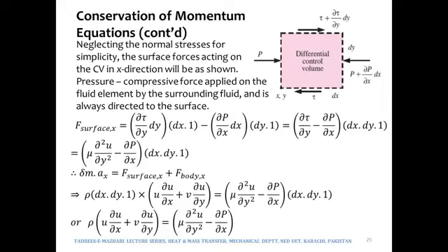So the same form of Taylor's expansion has been made use of, or you may simply call it a unitary method. So the difference of tau and this thing would give us ∂tau/∂y times dy. So it has been written over here, and since it is shear stress and we are talking about the force on the left hand side, this shear stress needs to be multiplied with the area so as to get the force. So the area that this shear stress is